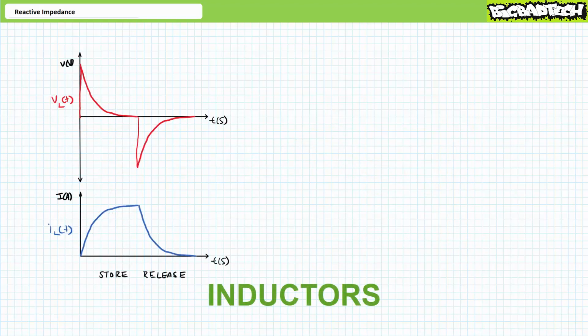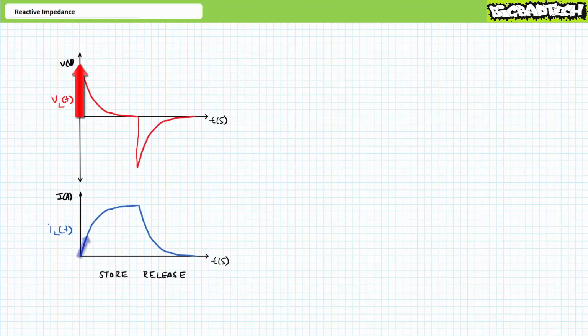You recall inductors in DC systems experience an expanding magnetic field, which creates an oppositional voltage surge. The oppositional voltage surge initially chokes current and then fades over time as current increases. Energy is stored in the inductor's magnetic field. During the release stage, the inductor's magnetic field collapses. The collapsing magnetic field generates a transient voltage pulse that temporarily continues to push current in the same direction and then fades over time. Any energy stored in the collapsing magnetic field is released.